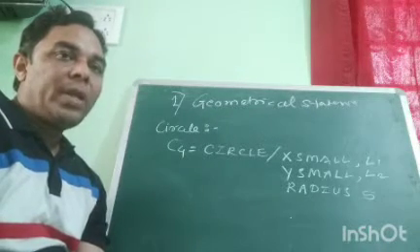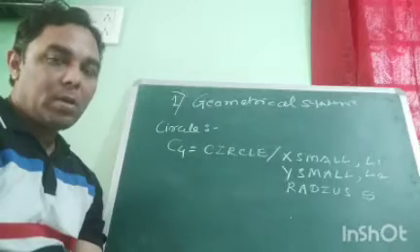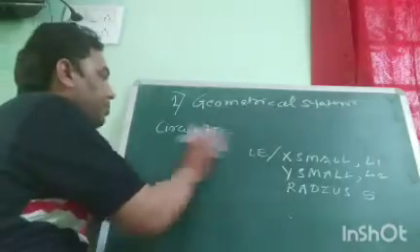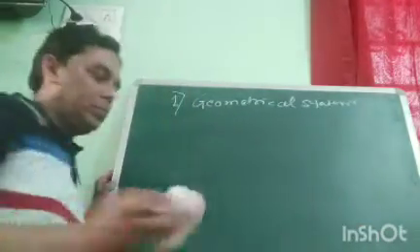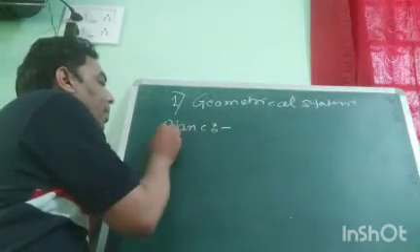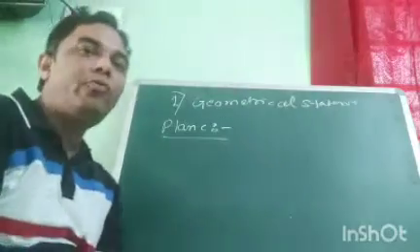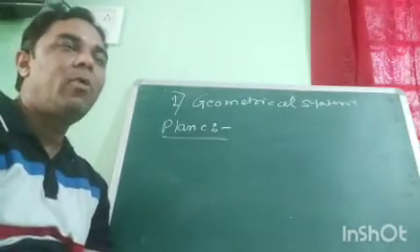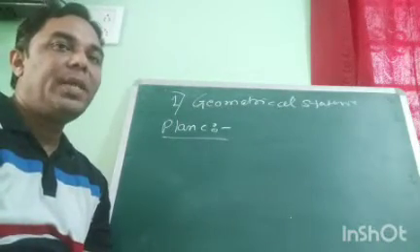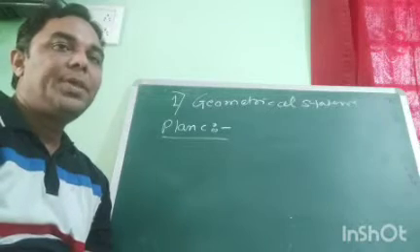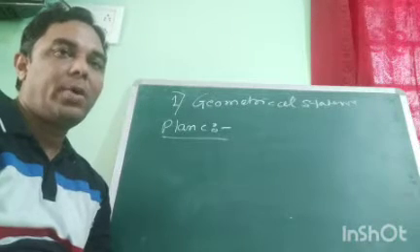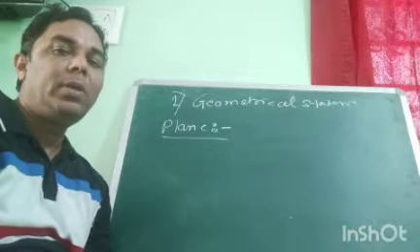Now, how to create a plane in APT part programming language? Let's see. Plane. First of all we need to understand how to form a plane. The plane can be formed with the help of a number of lines and a number of points. So here we are considering the points. Basically, when we consider the points in the syntax coding, by default the software forms a line in between a number of points.